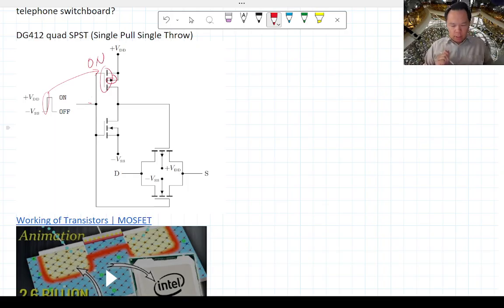This turns on this side. When this little arrow goes into the transistor, it's a negative edge, meaning that it turns on when the input voltage goes from high to low instead. Okay, so let's do the case where it turns on and see what happens.